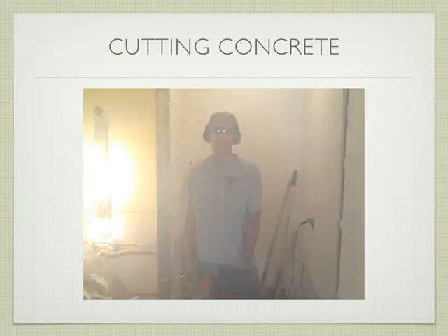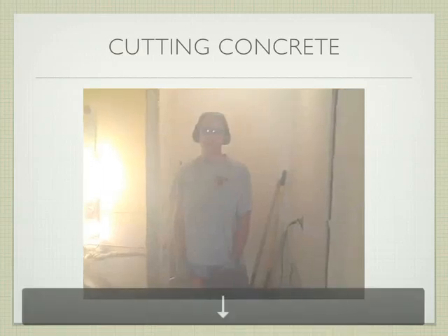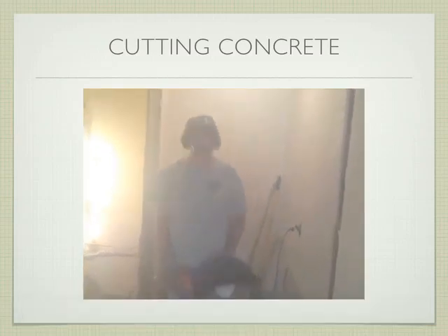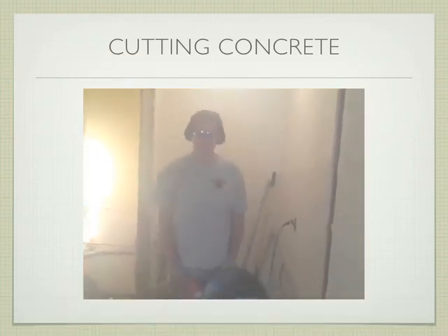And so this is a slab on grade. 4-inch thick slab, followed by the pea gravel, followed by the moisture barrier, followed by the capillary break, exactly like we were anticipating. And below that, we had to dig down about 4 feet to get into the sewer line, which happened to be relatively close. So we were somewhat lucky with the position of this particular shower. So here we go. We're about to cut through the slab floor here. You get the idea.